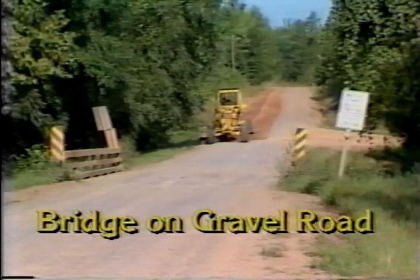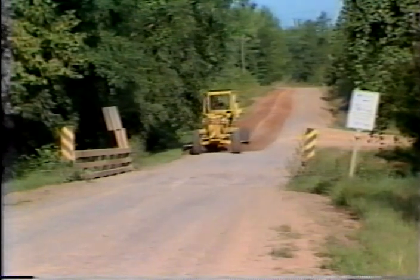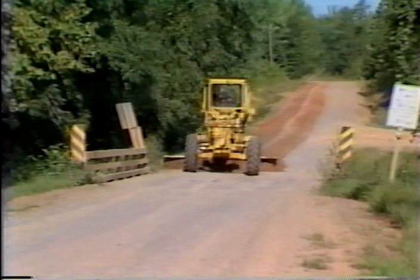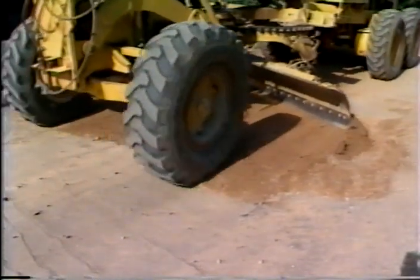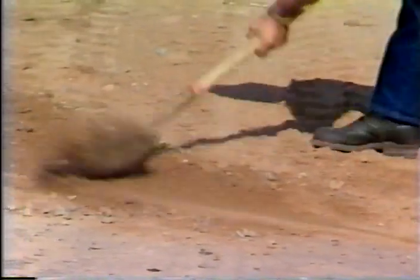The next special condition is a bridge on a gravel road. Gradually eliminate crown 50 to 100 feet back from the edge of the bridge. Transition the road to match the shape of the bridge at the intersection point. Be careful not to leave excess loose aggregate on the surface of the bridge, as this could create a safety hazard. To eliminate this, lift the blade at the edge of the bridge and backblade across the surface of the bridge to remove the loose material. When necessary, use a shovel to remove excess material.